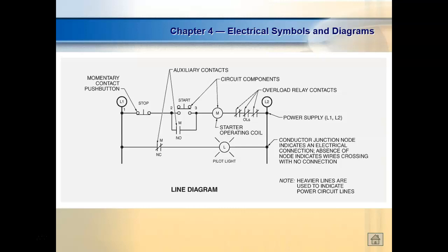Well, the overload senses current. If you wire for high voltage, it would pull less current. If you wire it for low voltage, it would pull more. So you have to have the ability to set the overloads or change the overloads to match the motor. So all your dual voltage motors will have external overloads. Your single voltage motors will probably have internal overloads. That makes sense. So dual voltage motors, I've never seen run more than 2 voltages. Ours is a dual voltage motor. And so I will show you all the overloads. This is the actual circuit hooked up here, by the way.